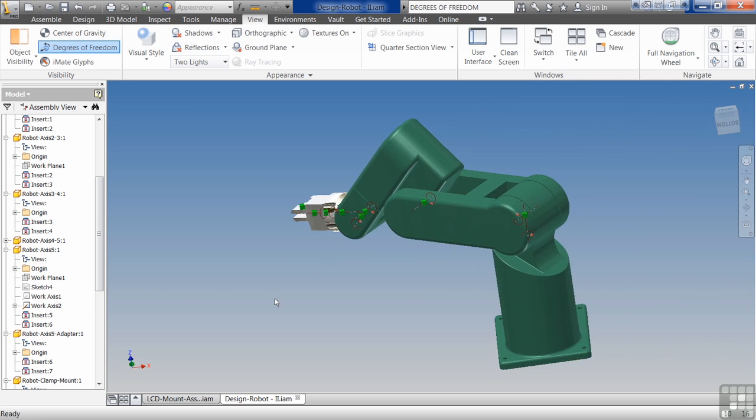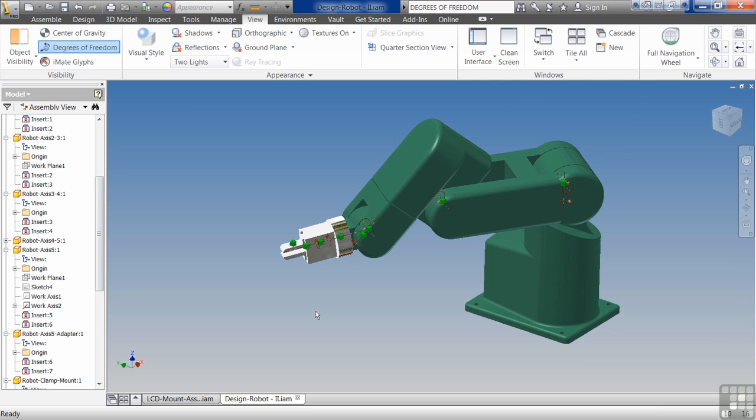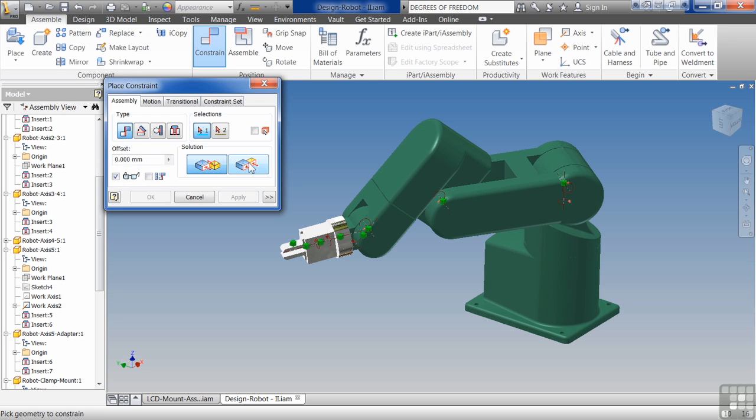So remember, if I say a constraint and we're talking about putting something together, we're talking about an assembly constraint. If I say something about a constraint and we say, for example, perpendicular or parallel or tangent, most of the time those are sketch constraints involving sketch geometry. Whenever I talk about assembly constraints, I talk a lot about things like mates and flushes, angles, insert.